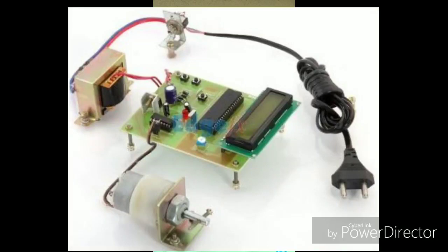I'll give you some of the basic applications for this project. The circuit can be used to drive a single DC motor without a motor driving IC. The circuit can be extended to two motors by implementing a dual H bridge connection. We can also use this project in simple robotic applications to control the direction and speed of a single motor. So this was the description of my project.